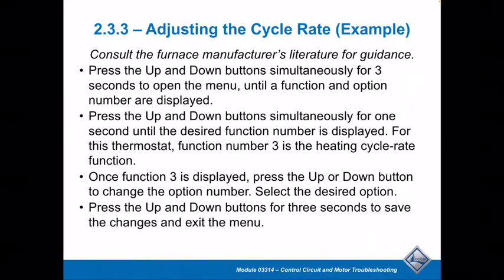And if it's an air conditioning unit, maybe you don't want it to be more than 3 times an hour. So I usually look at it this way. I said, whatever the cycle rate is, take that and divide that into 60. So if it were 3 cycles, that would mean it would generally turn on and off once every 20 minutes. 60 divided by the 3, and that's usually how I look at it.